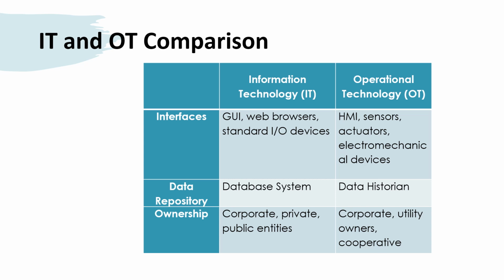Another feature that is found on historians but not on database systems is the more powerful compression capability. This feature is necessary due to the huge amount of volume that is stored in it. Just imagine the amount of data collected when the historian is set to collect the information in several sensors every 10 seconds, every hour of every day for several years.